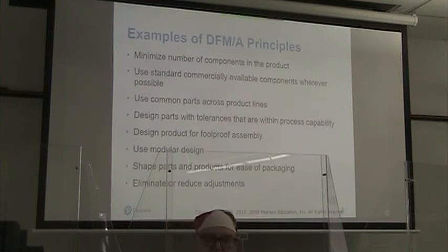Design parts with tolerances that are within the process capability. This is one where a lot of designers fall down. They start specifying too fine a tolerance, when in fact a looser tolerance would be perfectly okay.